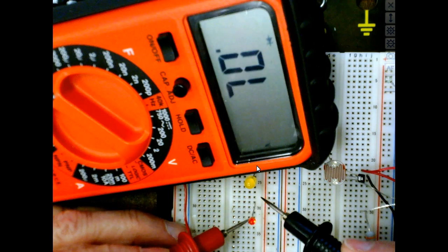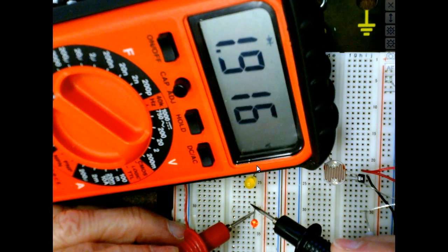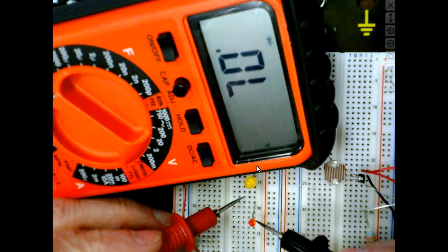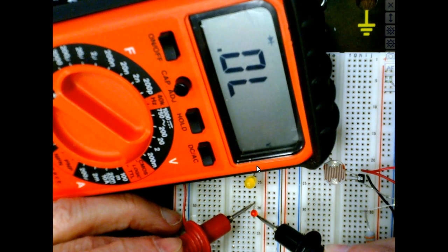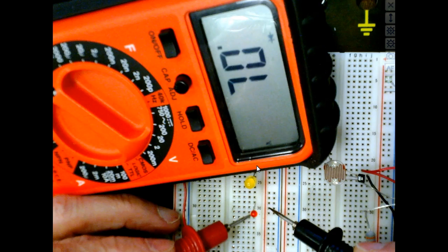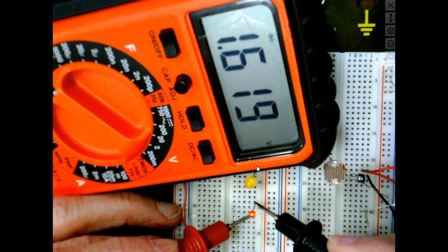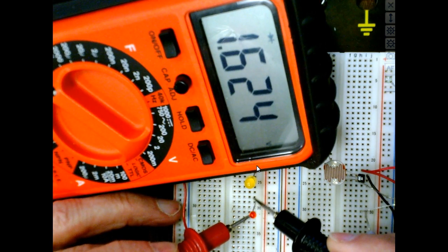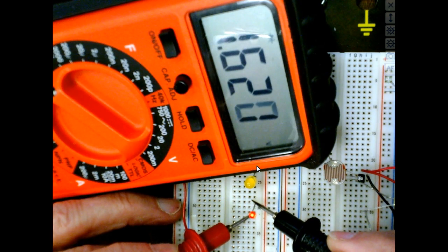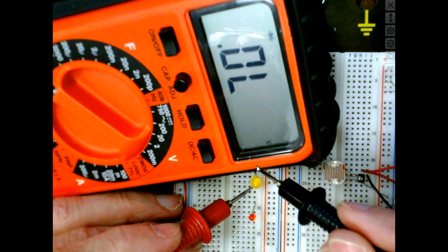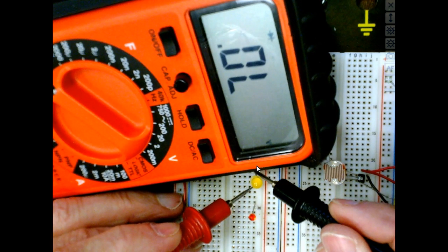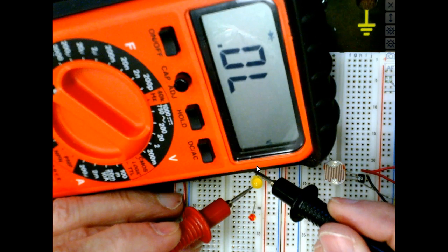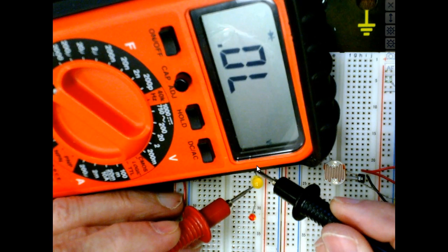See it? Forward bias, reverse bias. Forward bias, so this is red. This has a VF of about 1.6 volts. See, so they're not the same. But notice this one, can you see it actually come on? Don't expect that all the time. It depends on the size of the LED. So I can check this one, and you won't see it come on. Oh, yeah, it does too. Barely. Can y'all see it?